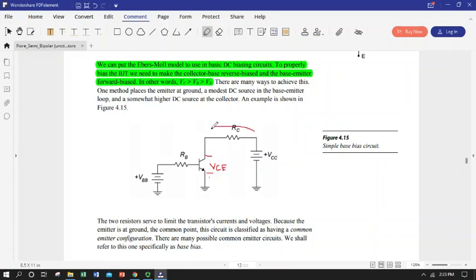And we have some collector current flowing, and we have very little base current, so I sub C is approximately equal to I sub E. So here's our collector emitter voltage across our transistor. So we could write our Kirchhoff's voltage law expression for collector current.